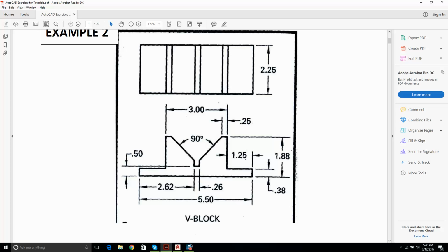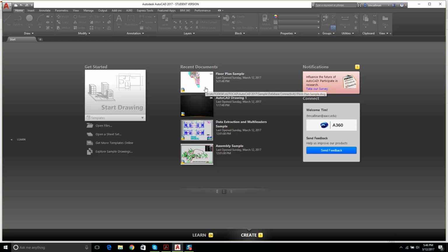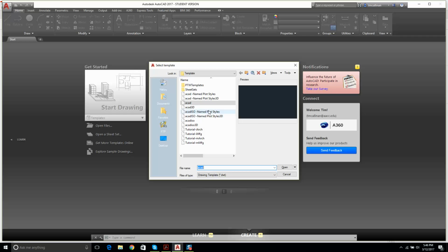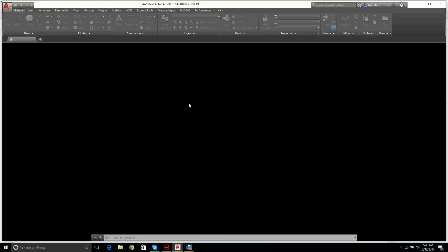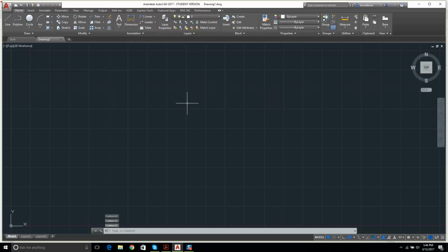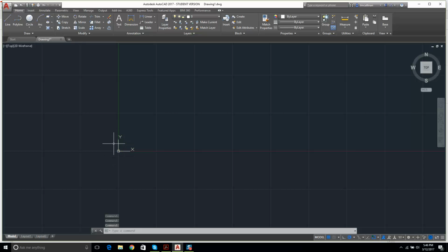Okay, so hopefully you have AutoCAD 2017 or 2015 or whatever installed on your machine there. And I'm going to click on New. We spoke a little bit about this, whether we would use the AutoCAD template or the AutoCAD ISO. Look, you may as well, hopefully you have this installed properly. I would use the AutoCAD template, right? And this is our origin here.